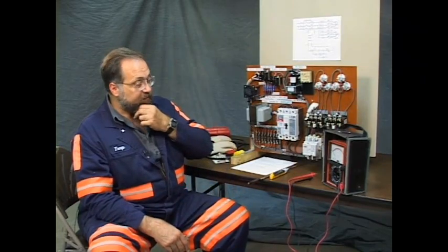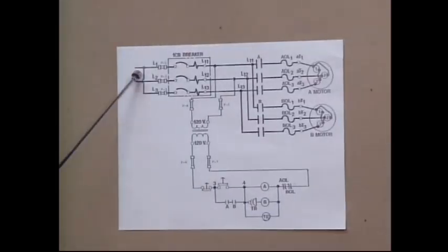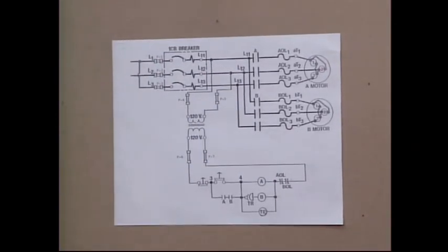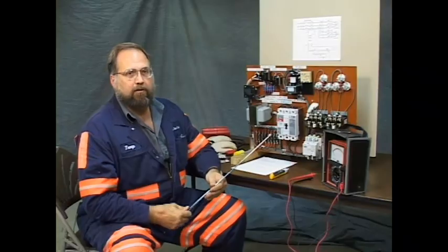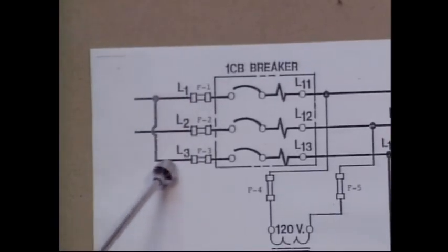Now in reality, a 3-phase AC motor wouldn't start on a single phase condition. That's not really an accurate illustration of a problem that a man might encounter in the mine with 3-phase AC electric motors. But on this trainer, to illustrate the 3-phase motors, you only have 120. You have a phase and a neutral. And to show 3-phase motors, you'll note there's a jumper from phase 1 to phase 3.